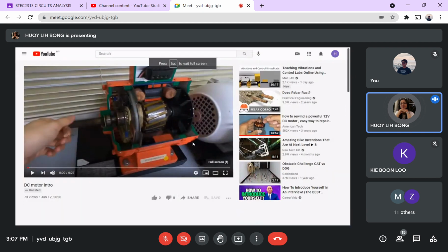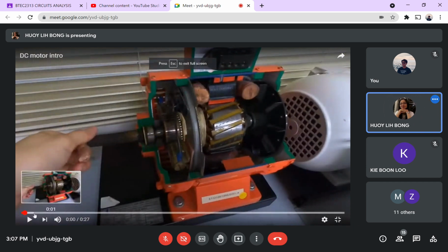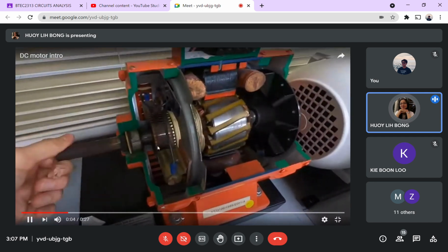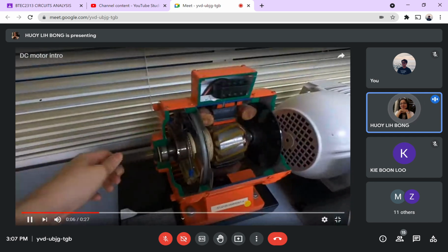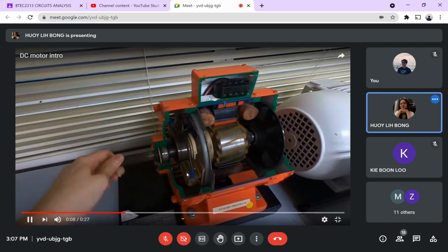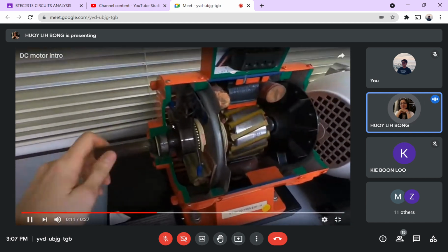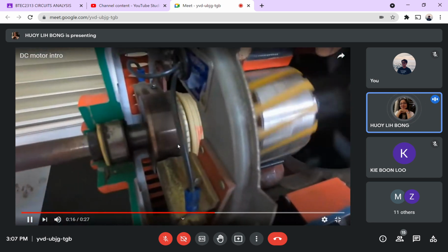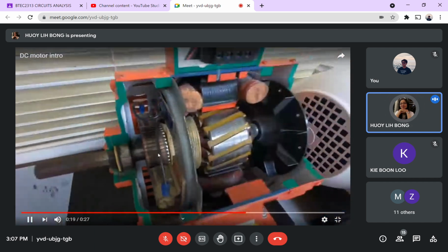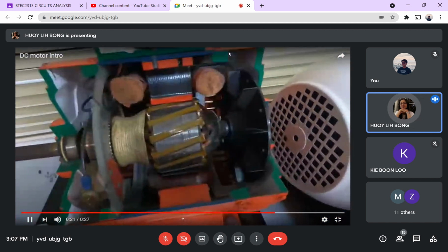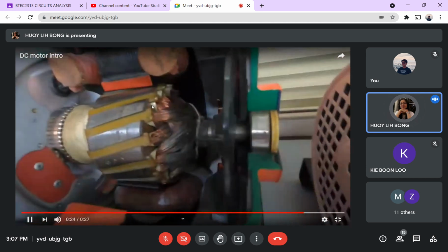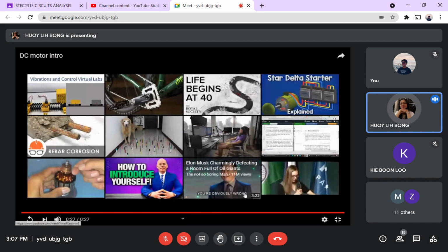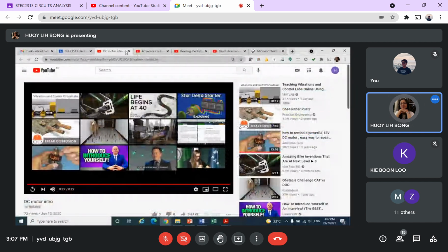If you're in the lab, you can see this cutout in the lab. So this is the shaft. If the machine turns, in the front here you can see the brush. Inside here, there's another brush to rectify the AC to DC. If it's a generator, you have the induced voltage. If it's a motor, then you need to supply voltage. You have the terminal on the top. So you can see the ventilation fan, the bearing there, all the windings inside.